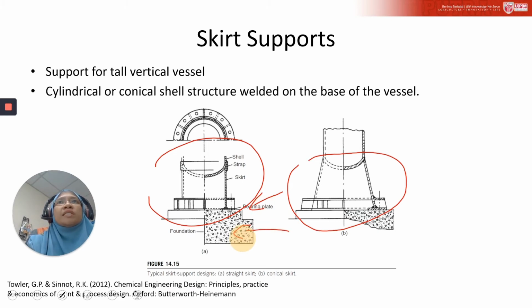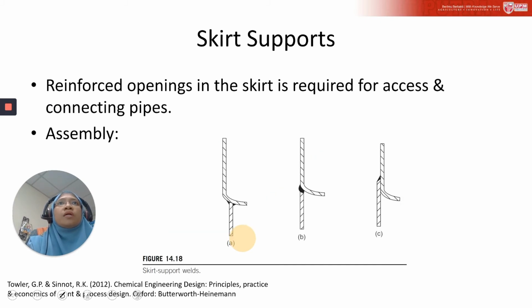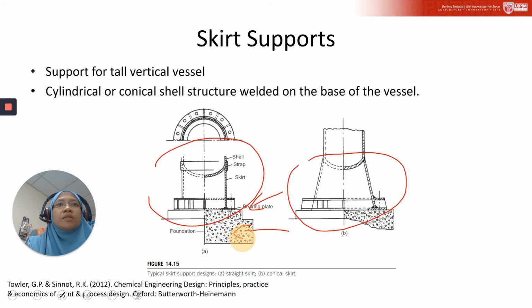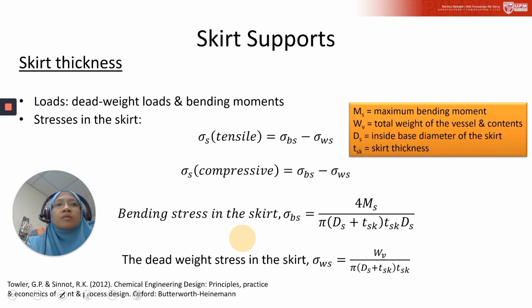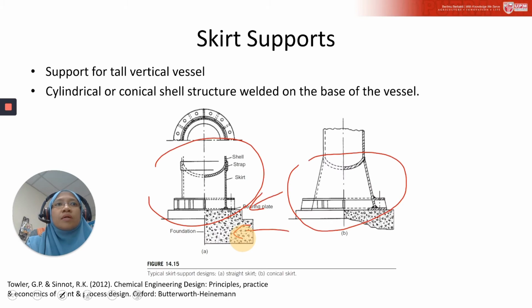So, for this skirt support, I did type somewhere here, but it's okay, I explain here. For skirt support, you need to include openings. Okay, so these openings will be used for accessing the bottom part of the vessel, and also for connecting the pipes. And this opening normally you need to reinforce.